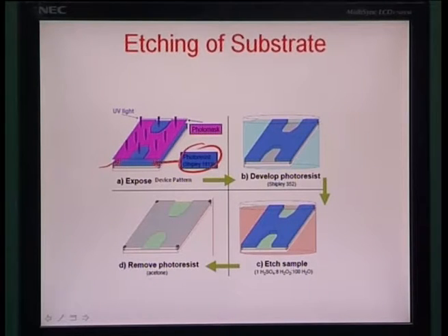So, wherever there is an exposure to light, there is going to be a creation of a via or a capillary. Then you add a photomask, as you are seeing in the violet region here. You then expose this whole assembly to UV after putting the photomask directly over the photoresist. When you hit it with light and then develop it, it creates two vias on the resist. The remaining portion is still the resist, in blue, and the portion shown by the two red arrows is where the resist is removed, or the vias are created.